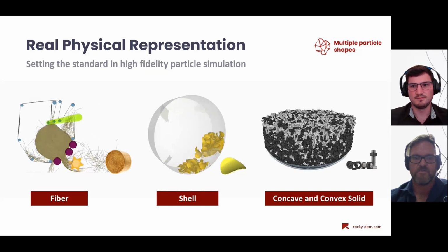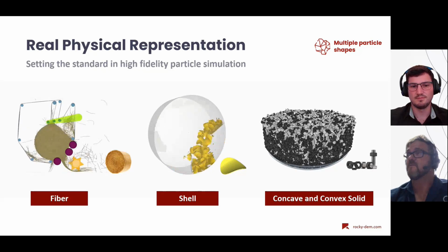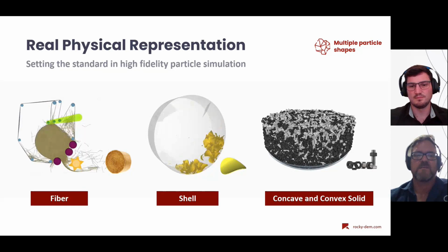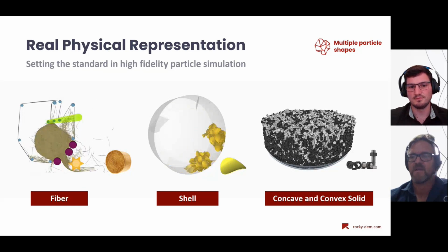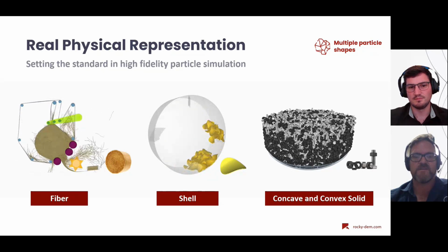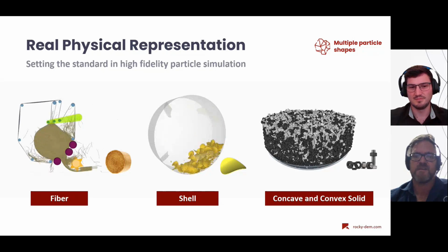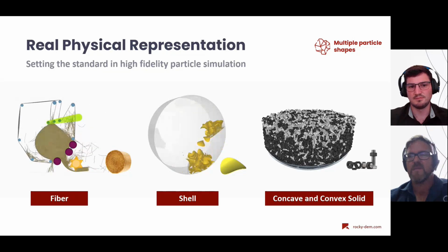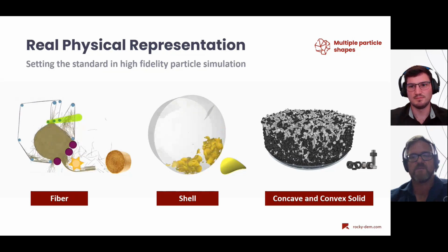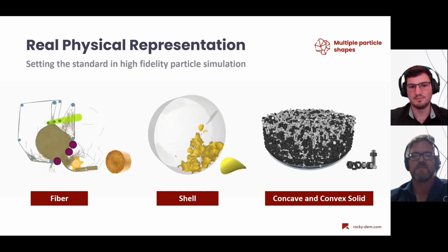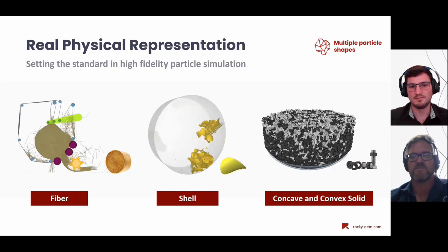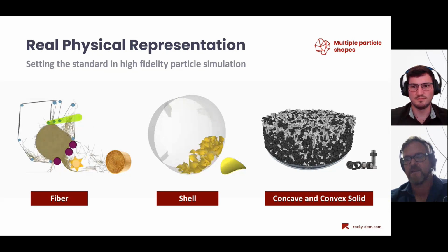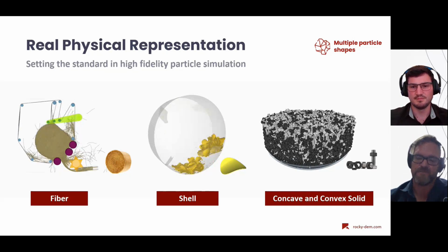You basically have to do an angle of repose test, and that's where you take a bunch of material in a cylinder, lift up the cylinder, and see what the angle of repose is. You'll build the same simulation in Rocky. Maybe a friction test to get the accurate friction, which basically entails putting a bunch of material on a steel plate and starting to angle that and seeing at what point it starts sliding. And I'll say something about stickiness and adding a couple of other things later in the presentation.